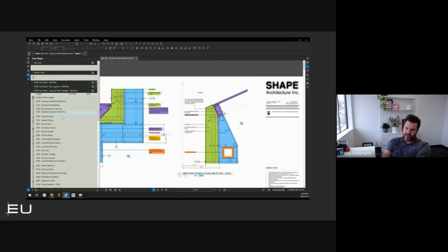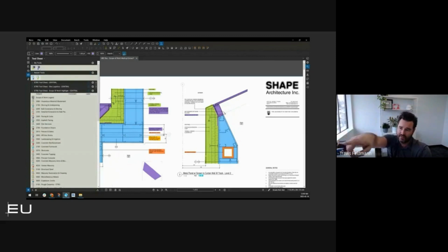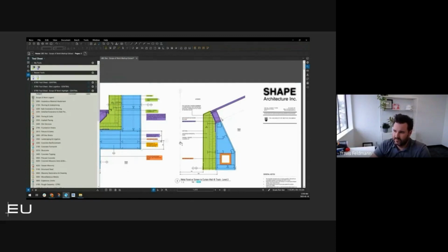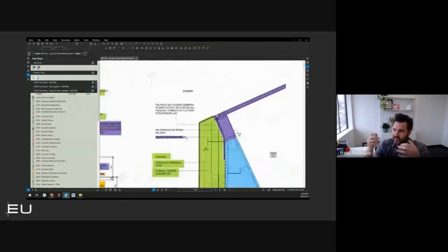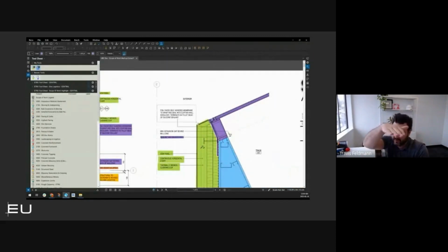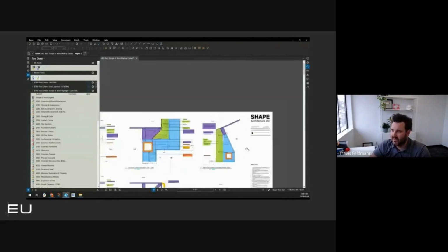So if you're going through a few scopes and they say you're using shotcrete, cladding and for whatever reasons structural steel as your divisions, you can bring those up into your recent tools and tag them as a kind of hotbar. So then that way, instead of scrolling through this list every time, it'll give you the availability to grab those more quickly as you're familiar with them for the day's markups. So now he's got hotkeys based on green is number one, purple is number two, and it just speeds up his markup review. So again, if you're doing envelope markups with curtain wall, you'd have your three sub trades, 1, 2, and 3 as far as hotkeys, and then it's just quicker access for those markups.